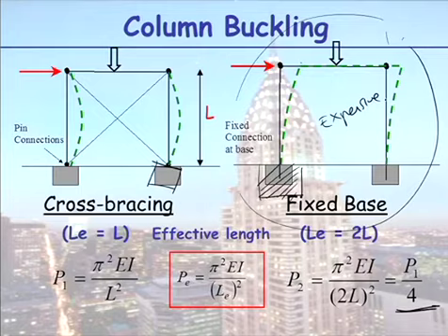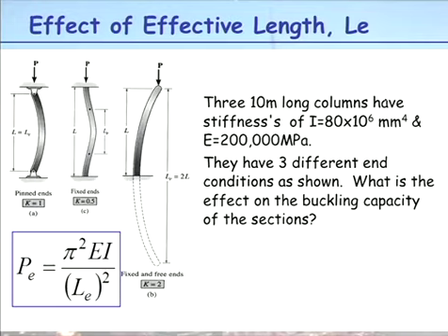So if you're building something more than a carport, a glass structure, and the architects say, no, I can't show any cross-bracing, of course it can be done. You'll do it by fixing the bases, but you'll say to them, okay, we need bigger foundations in there, and our columns will have to be bigger. How about you just make a feature of the cross-bracing, expose it, and make it look nice? That's the choice. Is that clear with everyone? So what your columns are doing affects your whole structure.